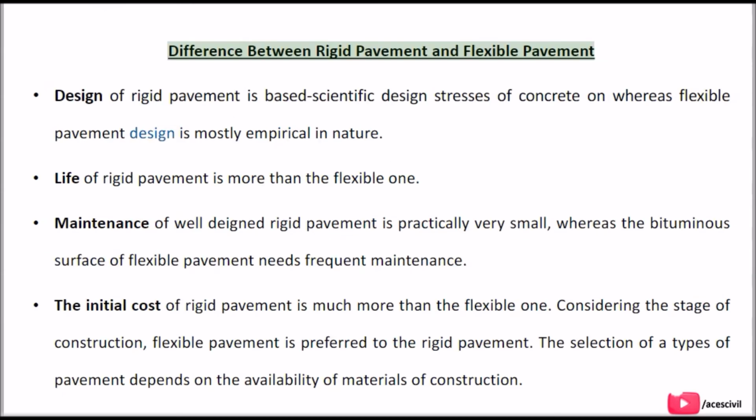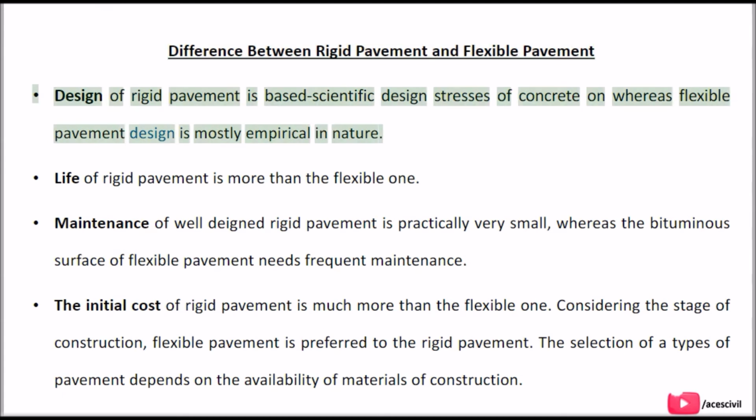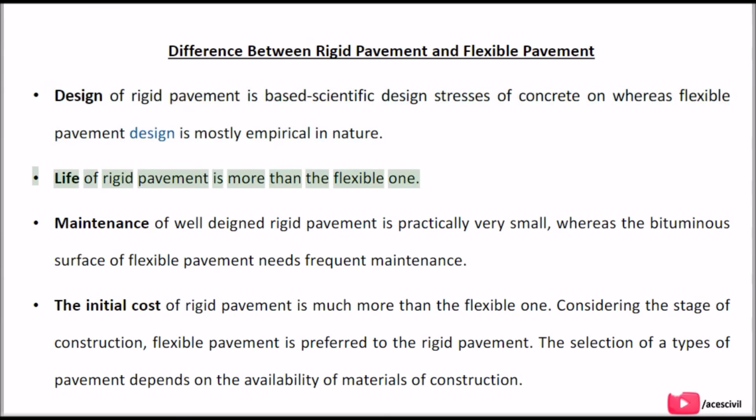Difference between rigid pavement and flexible pavement. Design of rigid pavement is based on scientific design stresses of concrete, whereas flexible pavement design is mostly empirical in nature. Life of rigid pavement is more than the flexible one.